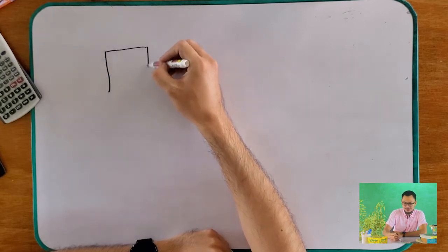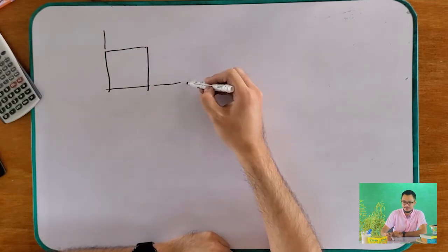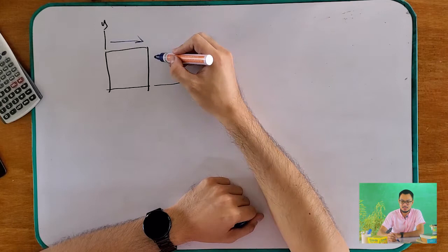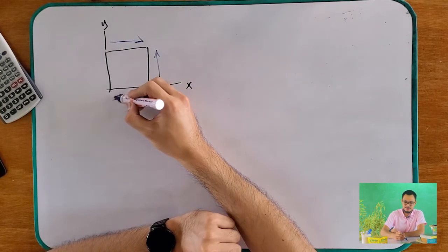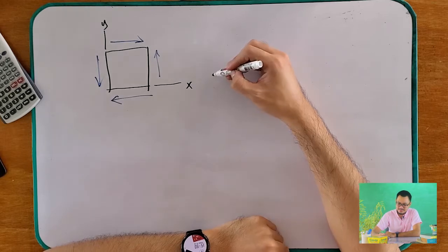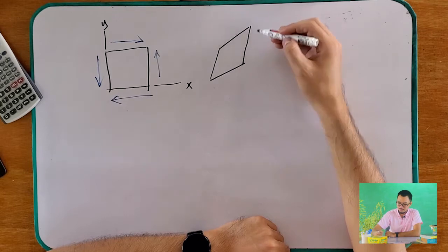As you can remember, if a square element is subjected to pure shear, we have learned the complementary property of shear, meaning that the direction of the shear should be either going towards each other or going away from each other. And once this material is deformed, it will probably look like this. Okay?